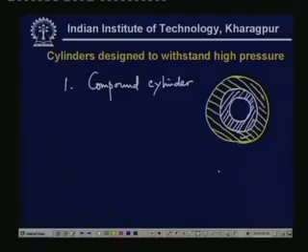What happens for this compound cylinder? Here we are going to see that a compressive stress is developed in the compound cylinder. Now, if the compressive stress is developed, then the material is under compression. So originally it is under compression, when we apply the external pressure here, then of course the tension develops over here, because there was initial compression. Now, even with tension, the maximum value of the tension does not reach that alarming level. So, this is one way to increase the strength of the cylinder.